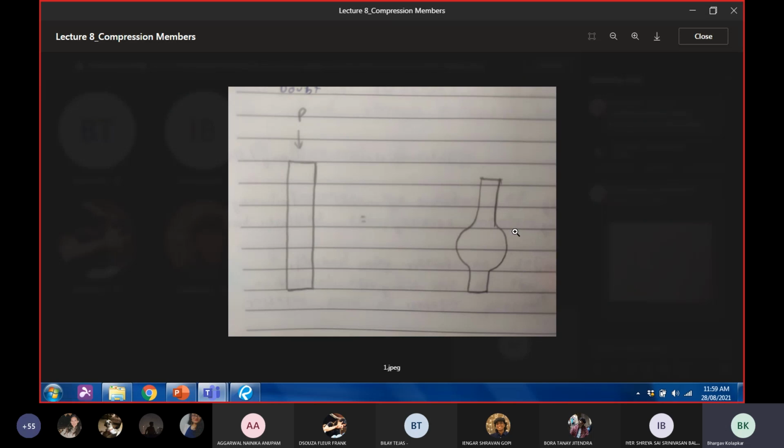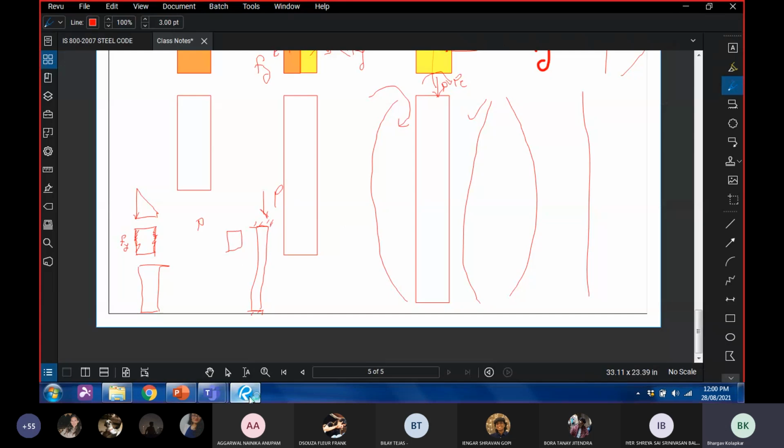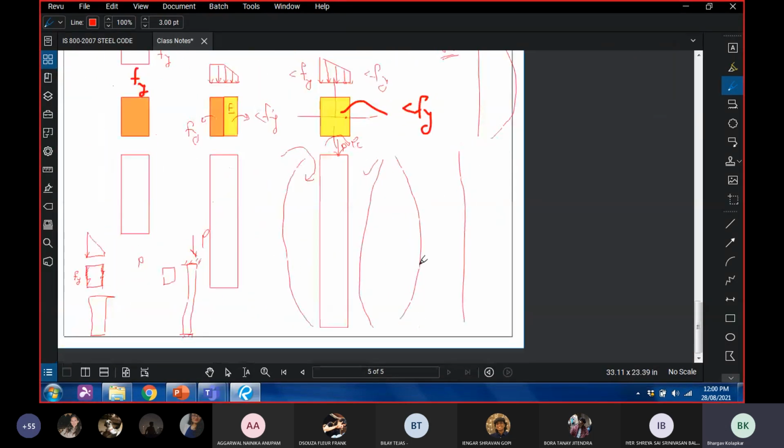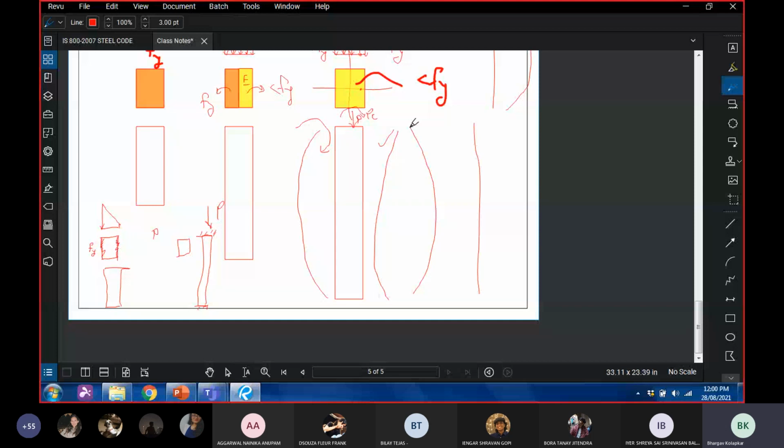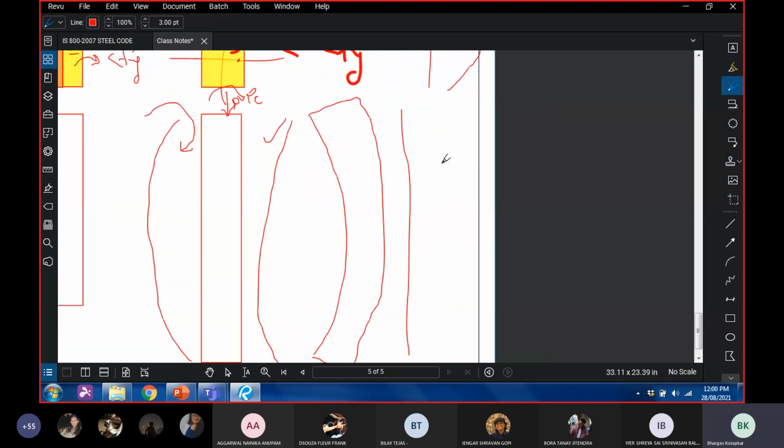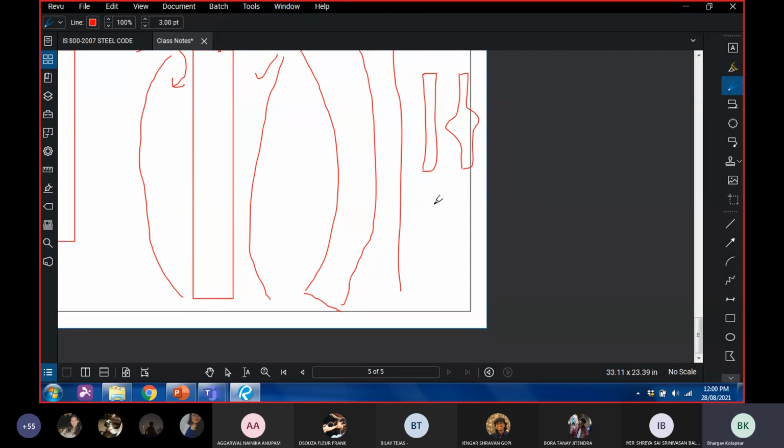That is really not relevant here because, let us see if I can answer this. When we are talking about a curve, this is the entire member that is buckling. What you've drawn is, say, if this is your member, you say that at squashing it happens like this, right? But it does not really happen like this, because under uniaxial compression, the entire member is under a stress that is the same.